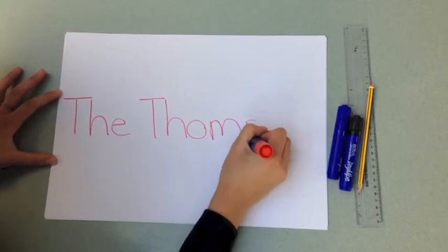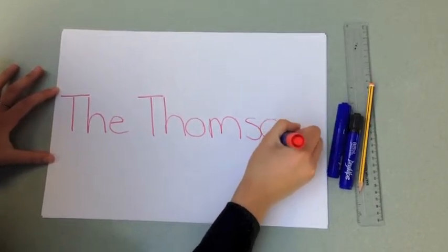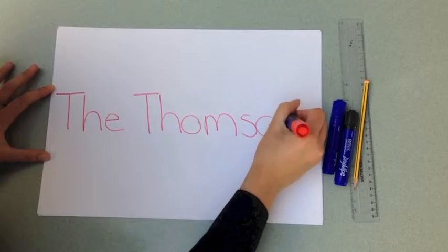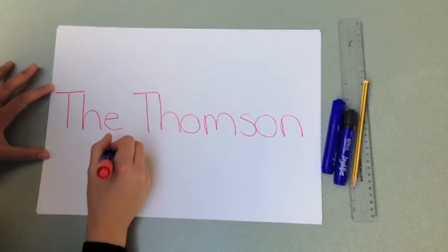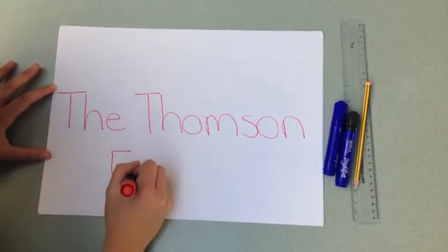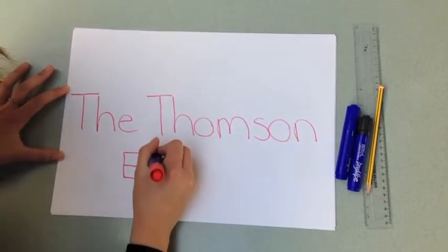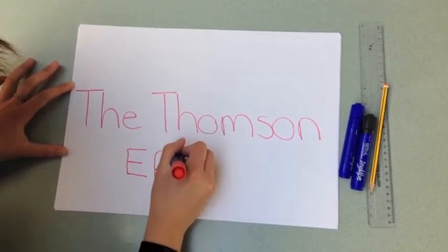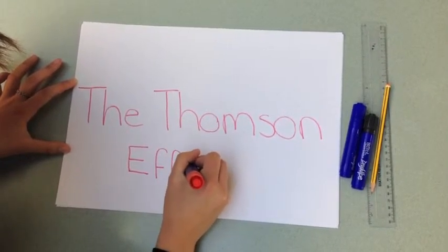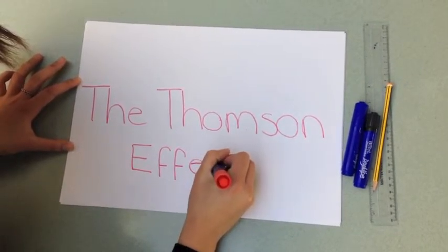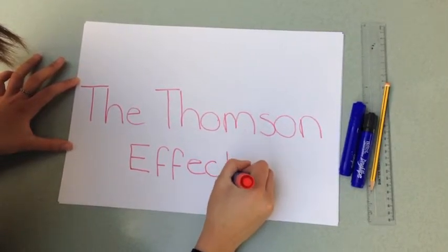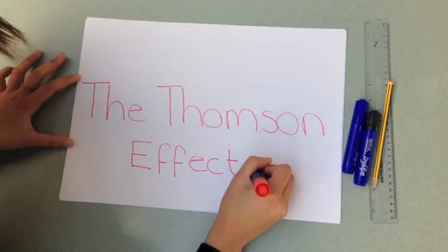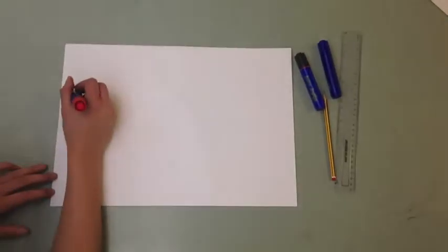If the metal emits heat energy when a current passes from the hot end to the cold end, then it is a positive Thomson effect. This occurs in metals such as zinc and copper. Metals such as nickel and cobalt give a negative Thomson effect as they absorb heat energy. The heat exchange with the surroundings is proportional to the electric current and the temperature gradient.